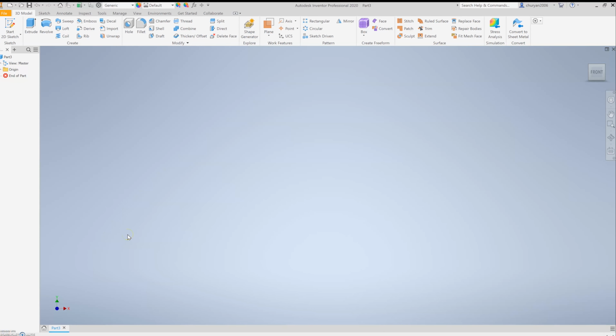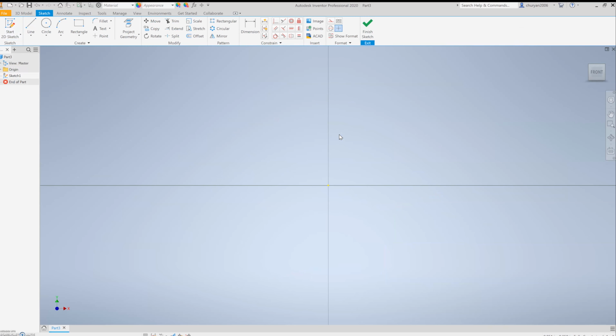For our first object, we'll be creating a cone. The first thing you want to do when you first start sketching is to break the final 3D shape down into simpler 2D shapes or parts. Since we are creating a cone, I am planning to break it down into a triangle. So let's draw a triangle with the line feature right here. This will allow us to easily create the object we want.